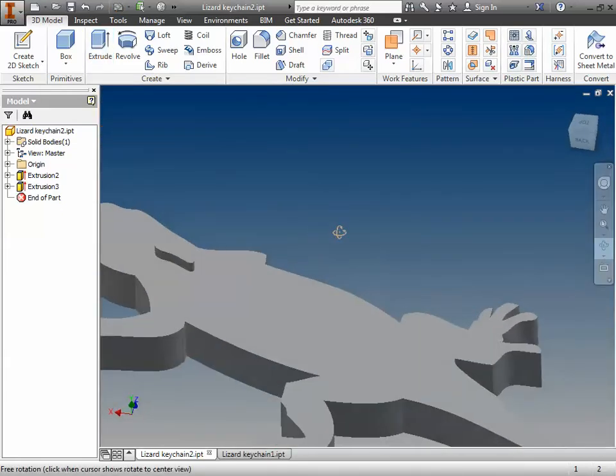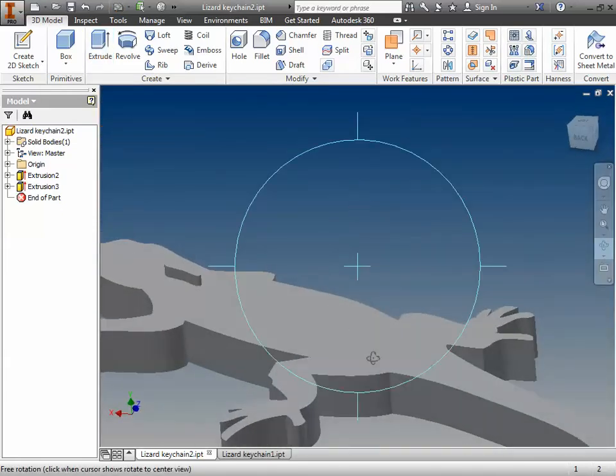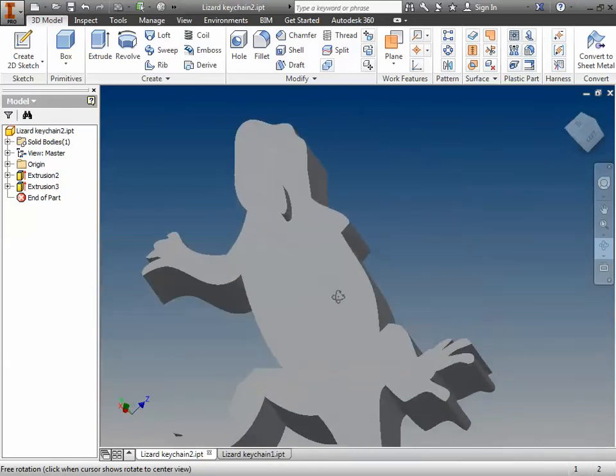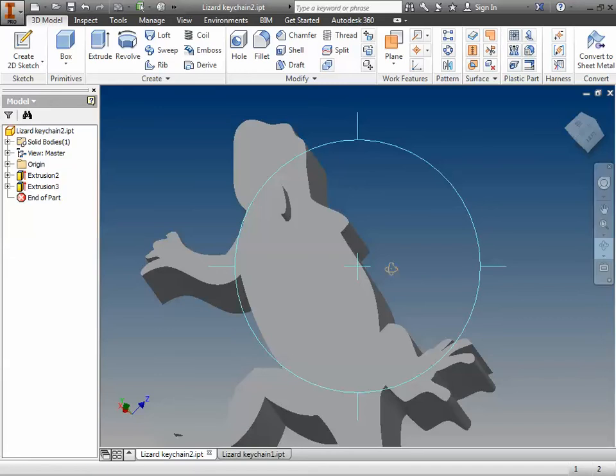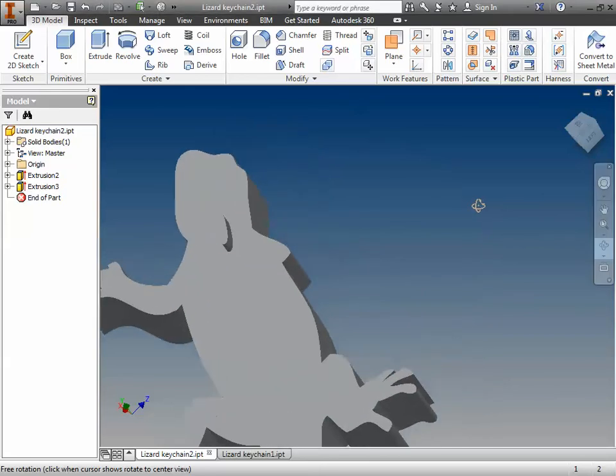But what I want to show you is you draw the surface, you draw the base first, and then you draw the details. And then what I do is I do the same thing again. I would draw this elbow, and I'd extrude it down. But the legs are supposed to be shorter than the body, so I'd probably mess around with that. Okay, so the next thing we need to do is probably take a look at making the hole in this thing. Okay, so in order to make the hole, I'm going to hit escape here.